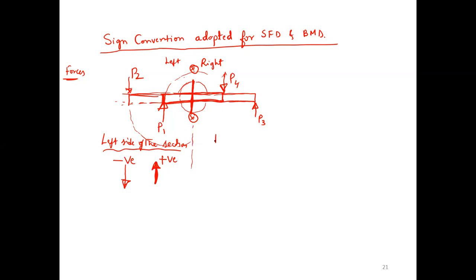I'm having two sections, right? Right side of the section. Now, how will P4 rotate with respect to the x-axis? It is rotating clockwise. How is P3 rotating? Anti-clockwise. So now tell me, all vertical downward forces on the right of the section will create which type of moment? Clockwise, so positive. All upward forces will create anti-clockwise, negative. Be careful when you are taking the sign convention.